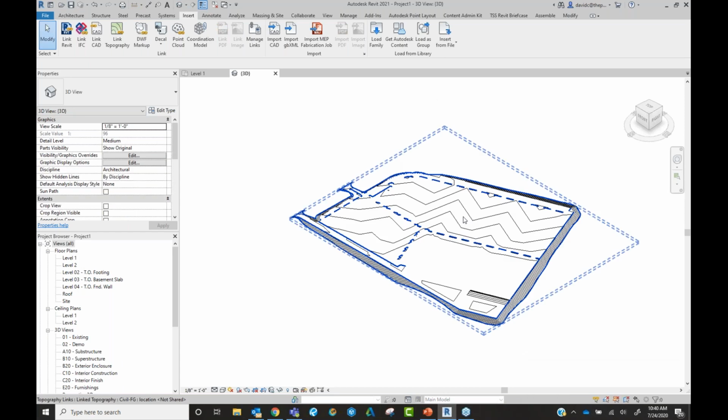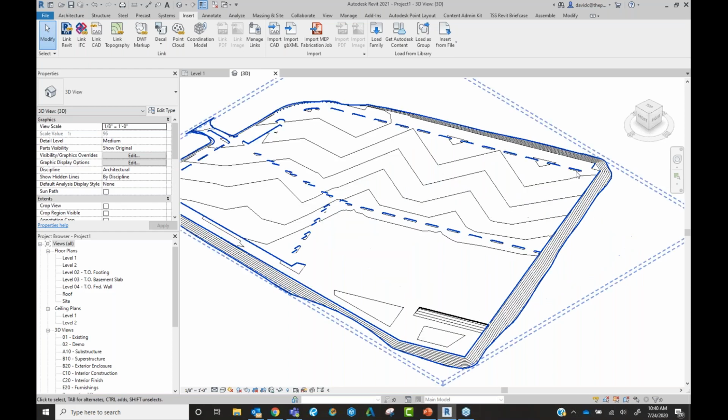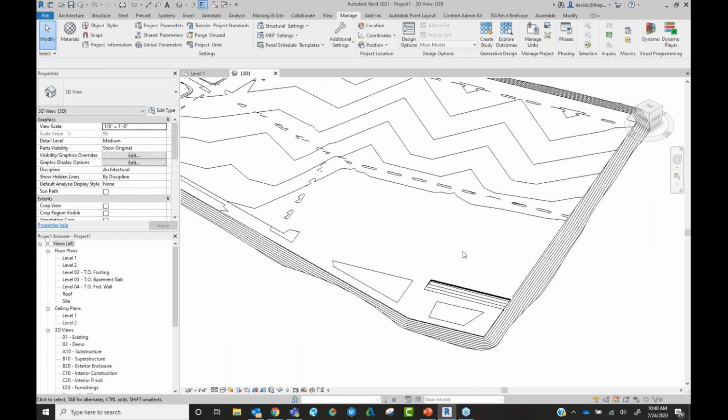So as I was saying a second ago, as things adjust inside of BIM 360, so as I go into CAD, I click on Arch. If Shelly were to update the versioning here, I could simply grab my link. So I go manage, I'll go manage links, find my topo, and here's where I can choose to reload that topo surface from this saved path. Now, if anything happens and they maybe saved another model up there, anything like that, it's a simple reload from, and then I can go ahead, pull that new path down and have my nice updated surface here ready to place my building on.